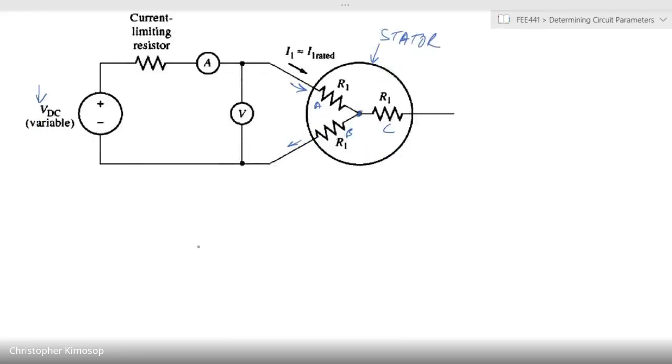In order to carry out the test, you will have a variable voltage supply that will slowly raise the voltage passing through the circuit until a point where your elements are not overheating. Remember, the load is not passing through. In this case, your motor is at a standstill and it is not operating in its normal mode.